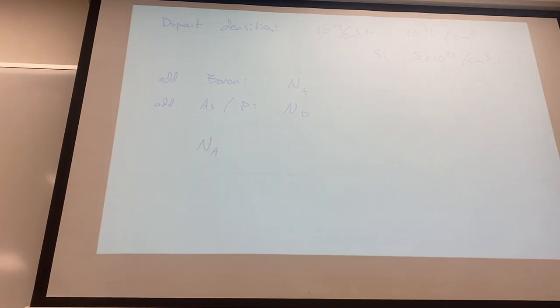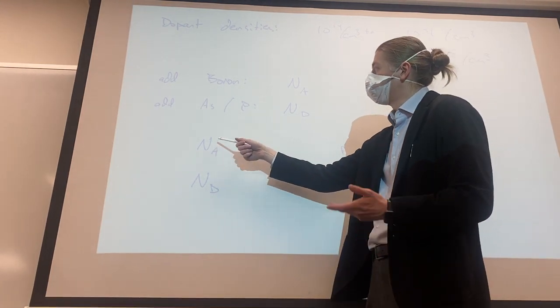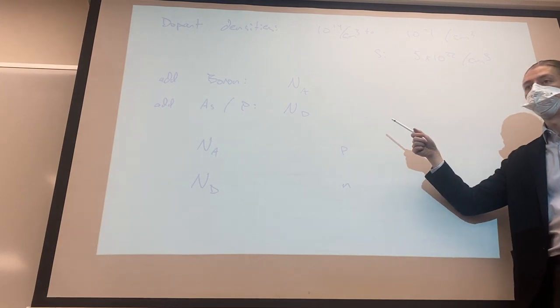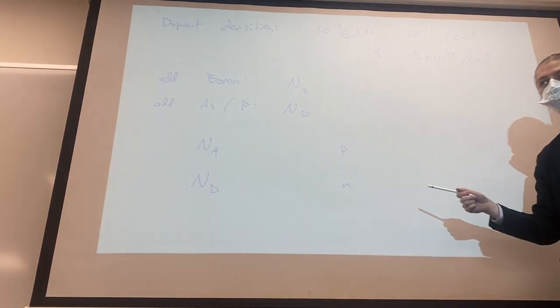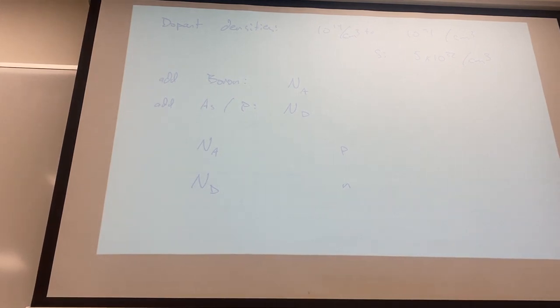The dopant density, Na or Nd, is related to what we generically call p and n, where these are the actual concentrations of holes and electrons that result. Right, so Na is the number of, in this case, boron atoms, and p is the number of holes that you end up with. They're close, they're always really similar, but not always equal. So they don't necessarily equal each other. This is the holes per cubic centimeter and the electrons per cubic centimeter. The new holes introduced and the electrons introduced.